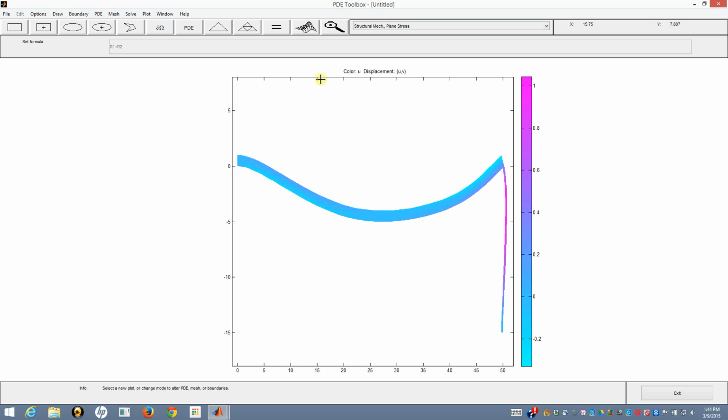It's overly done, and it's maybe over deflecting, so to speak. But from the way I did it, these are linear problems. First of all, I have to admit that these are all linear problems. So a 781 unit deflection on a beam is too much. As far as deciding to be linear or not linear, for a 50-foot long section that deflects 781, you realize that's too much.